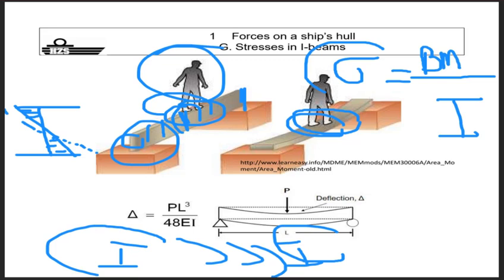And you know you have bending moment curves. You might have a bending moment curve like this over the entire length. It means that you have stress levels which differ depending on the place that you calculate, because you have different bending moments on every spot. And it is also depending on what? It's also depending on the distance from the neutral axis.